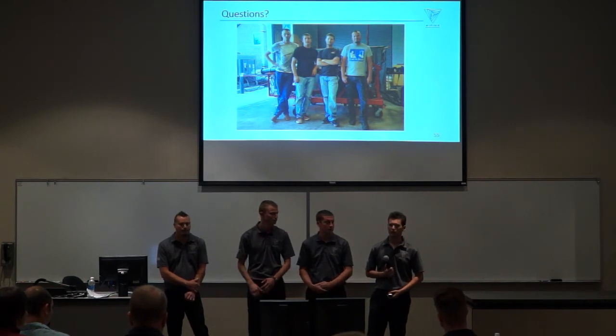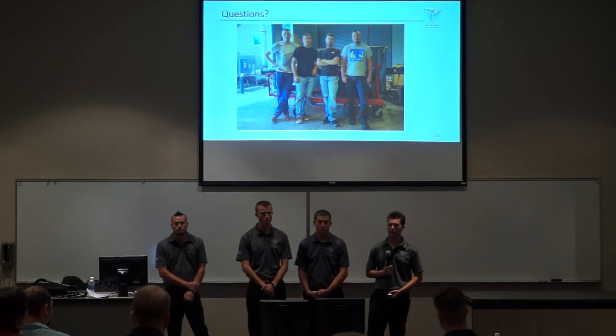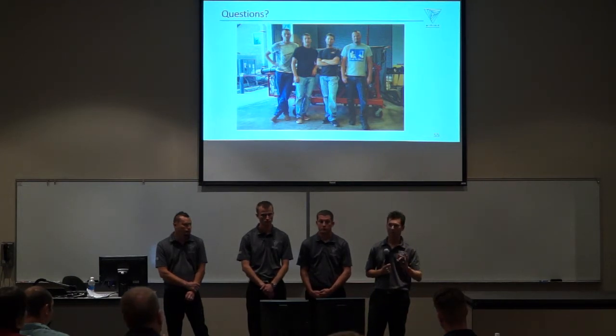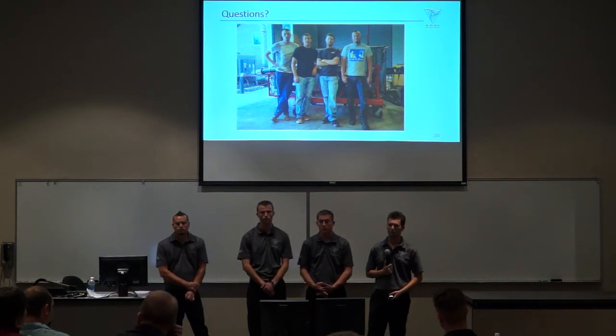No calculations going on it. We know that with the design of the V-gutter in the end, we wanted to minimize our pressure loss against it. And we know from before that afterburners of this size have always had a blockage problem, and that's too much pressure loss, which is why we opted for a single flame holder. That was to the extent of the design of that. Yeah, thank you.